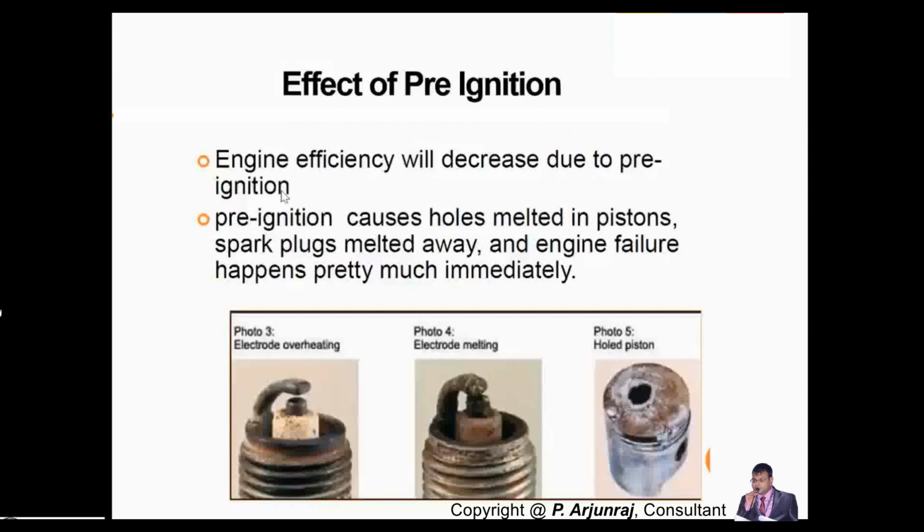Pre-ignition also causes faults, which will result in the melting of the pistons, and even the spark plug gets melted away. Because of the pre-ignition, it creates a temperature, and it will also overheat the spark plug electrode.